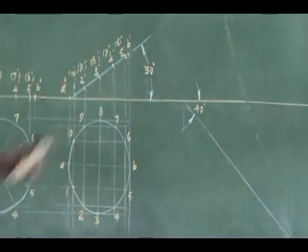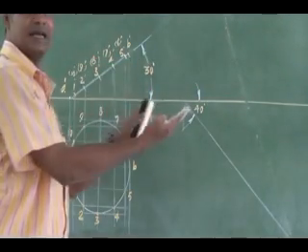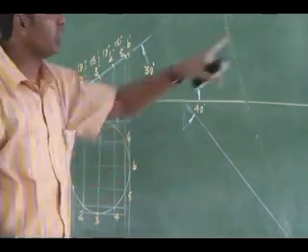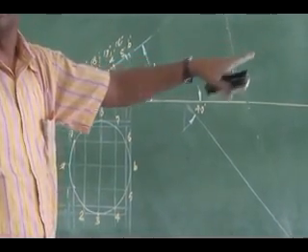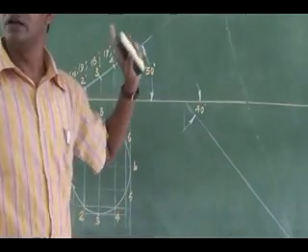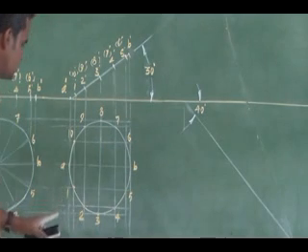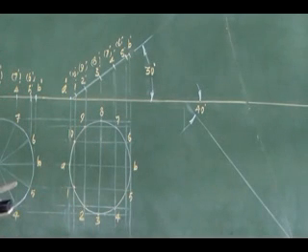But otherwise, see here, this box procedure for redrawing the top view: you close it with a box, and from the box you can reproduce the top view, right? Here it is easier. For circles, I can use another procedure.